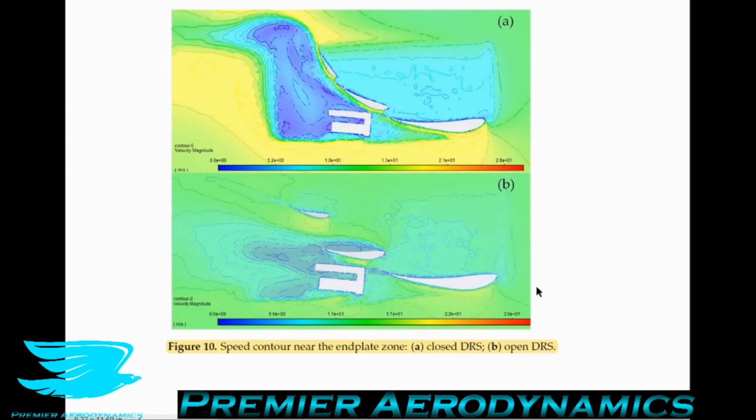To get a 0 lift coefficient, you need to put the angle of attack very negative. I'm not sure the exact angle of attack. It might be 2-3 degrees. But with that, you're going to get an increase in the drag coefficient as well. So here is the best situation to get the lowest drag possible.